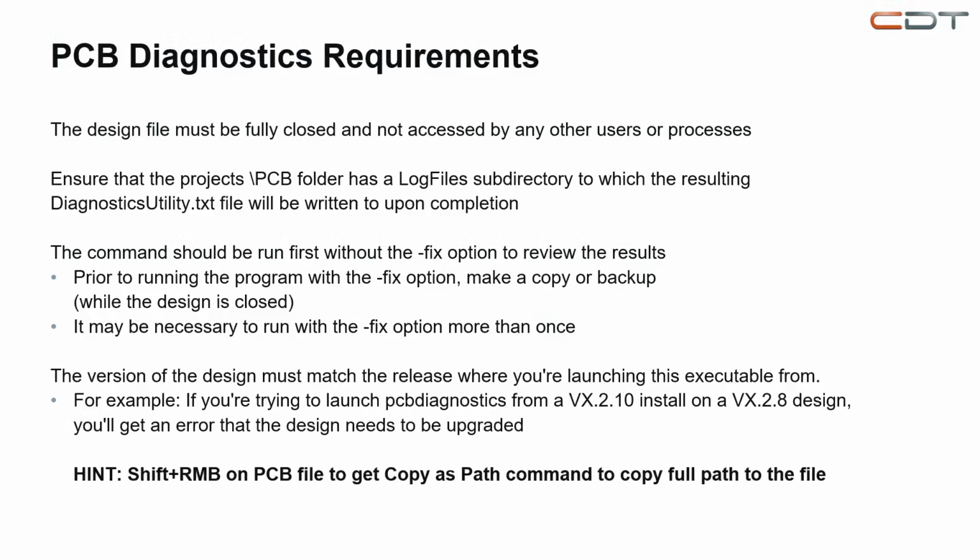Small hint: in Windows, if you want to take a copy of the path to the PCB file, you can use Shift and right mouse button click on the PCB file to see the hidden command called Copy as path. If you choose it from the context menu, you will have the full path to the PCB file in your buffer.